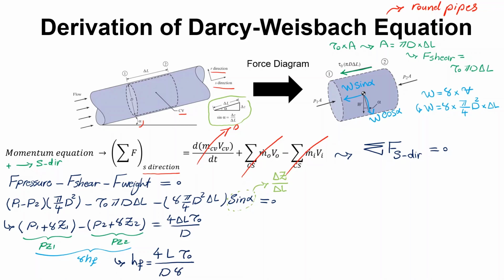Okay, so this is the equation that Darcy-Weisbach came up with. And in order to have this equation in terms that can be applied to laminar and turbulent flow, what they did is that they multiplied these variables by kinetic terms: density, velocity to the power 2 divided by 2. So they multiplied this equation by this, and then they reorganized it to come up with some familiar terms.